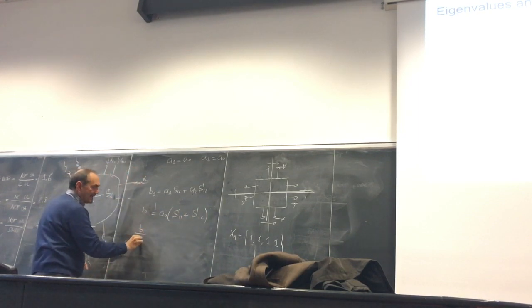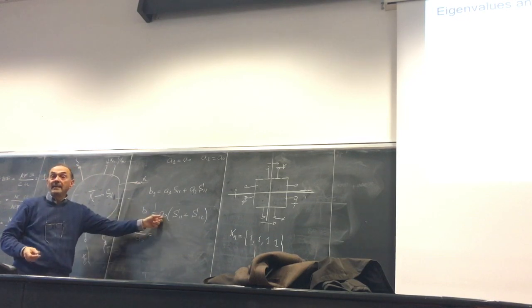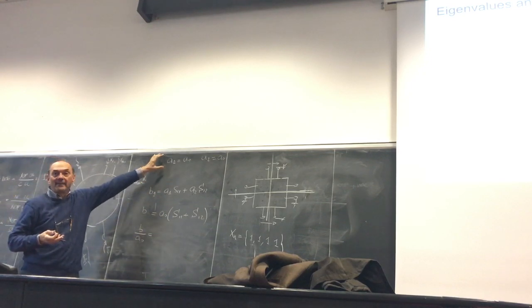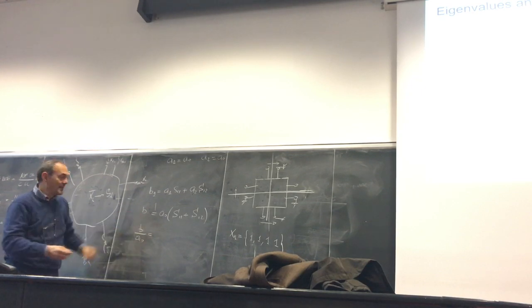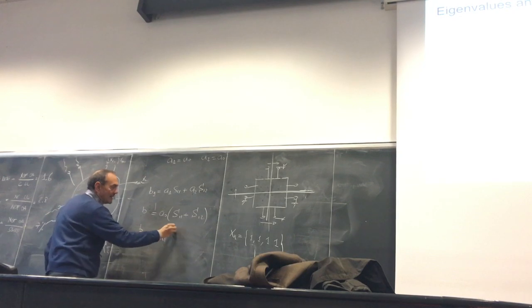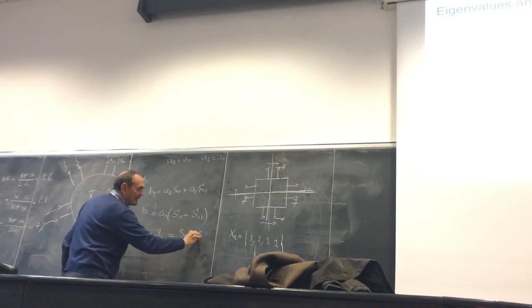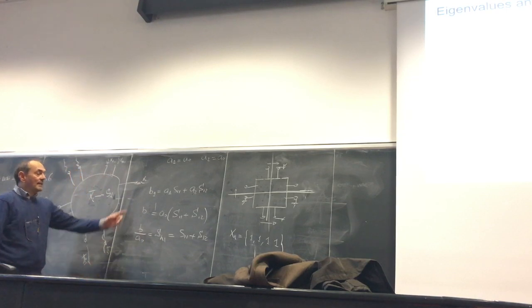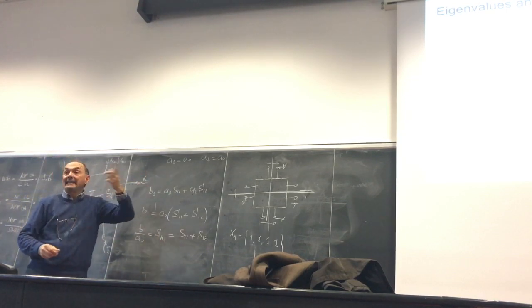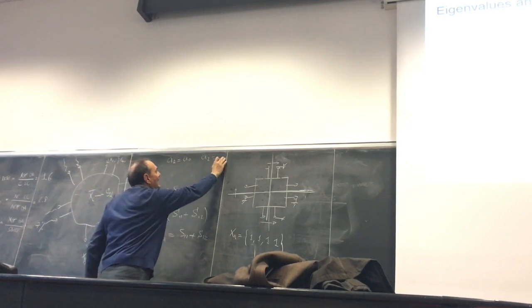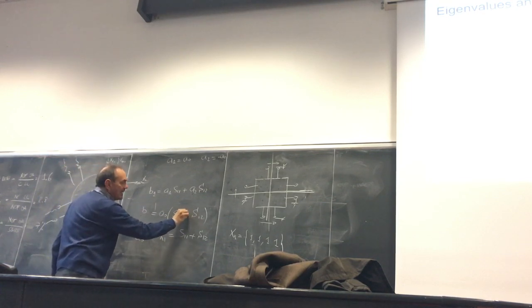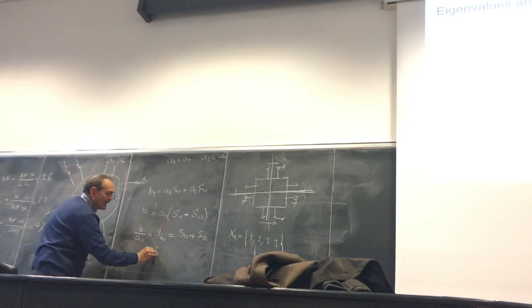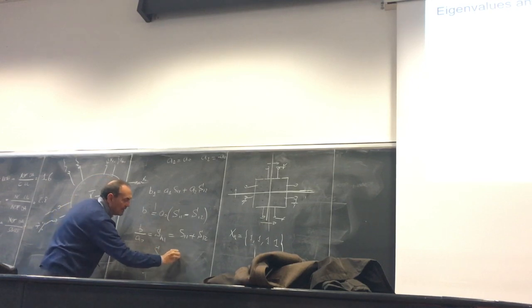And then B divided by A0. What is B divided by A0? I'm exciting with the eigenvector. Then B divided by the exciting element is the eigenvalue. So S lambda 1 is equal to S11 plus S12. In the same way, if I'm exciting with the other eigenvector, which is this one, minus A0, then the difference is that here I have minus, and then S lambda 2 will be given by S11 minus S12.